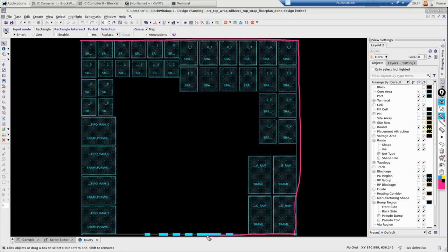So now how do you create this area? What calculations do you need to take care of? Is this area going to be good enough, or is it too much? How do you assess that you are looking at the right area? So we do die size calculation and then channel calculations, and then place the macros and decide whether you can rotate them. These are all the macros that we were talking about. These are all SRAM macros, SRAM memories of different sizes.